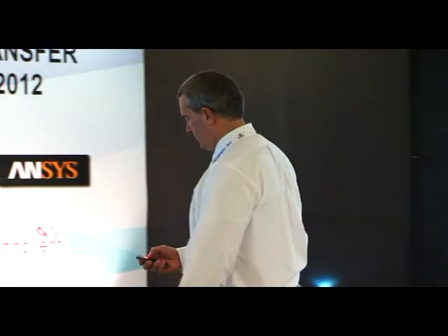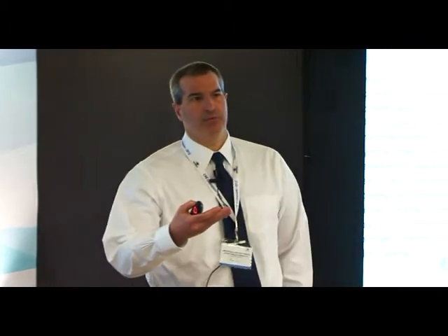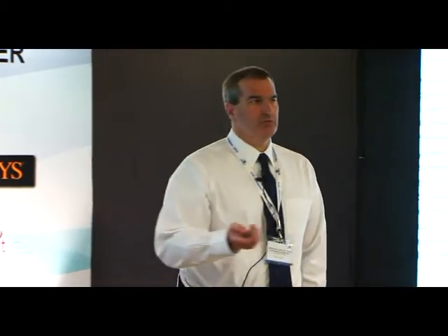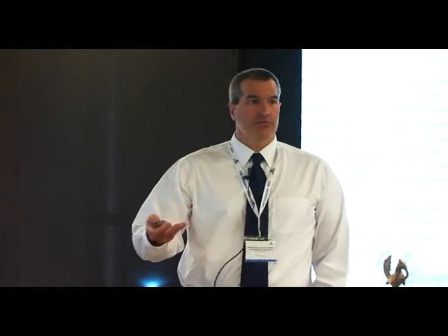As you might know, the high pressure turbine's job is to drive the high pressure compressor in a gas turbine engine. It operates in a combustor exhaust stream, which is about 1600 degrees C, plus or minus, and you want to continue to drive that number up for increased performance. The issue you run into is that even your single crystal nickel superalloys are only good up to about 1150 in terms of their material capabilities. And so you have to use both passive, like a thermal barrier coating where they coat the blades with ceramic, or active cooling technologies.